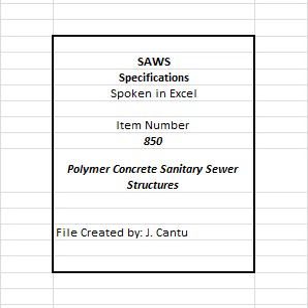850.6 Testing. The contractor shall notify inspector and engineer 48 hours prior to beginning of structure testing. 1. The contractor shall perform the testing for all sanitary sewer structures in accordance with the following. 2. All structures must pass a leakage test. 3. The contractor shall test each structure, after assembly and backfilling, for leakage, separate and independent of all other sanitary sewer piping, by means of either a hydrostatic test, vacuum test, or other methods approved by the engineer. 4. The contractor is hereby instructed to conduct either of the two identified tests in the following manner.